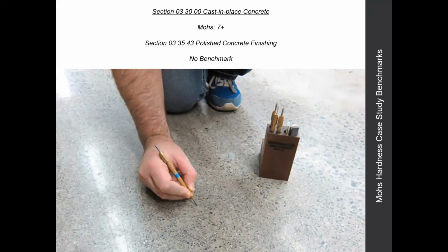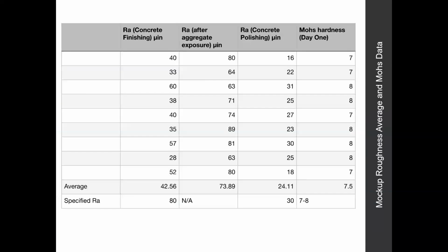So what does this mean? Well, it means your concrete's really, really hard, very, very quickly. So now we start thinking a little bit holistically about the rest of our schedule. We're going to have scissor lifts and wrench drops and spills and all sorts of things. What are the change orders going to look like if your concrete is measurably as hard as, say, dry shake hardener already versus softer at about a 5 or a 6? You're going to spend more money. You're going to absolutely have changes to the aesthetics that aren't necessarily going to be welcome. So again, it's one of these simple ways to measure what you're handing over to the client.